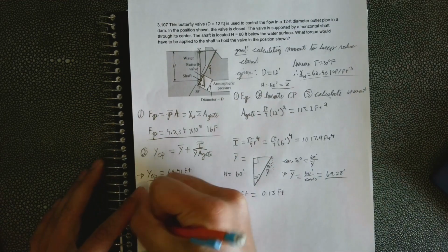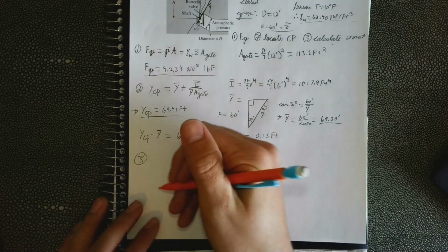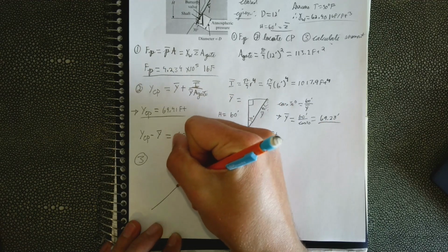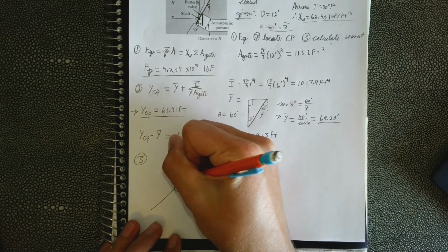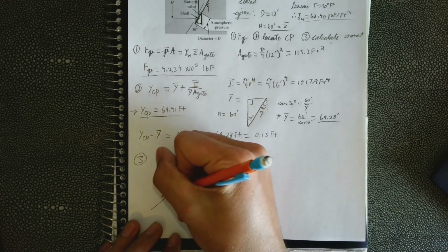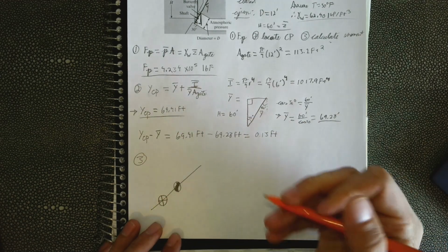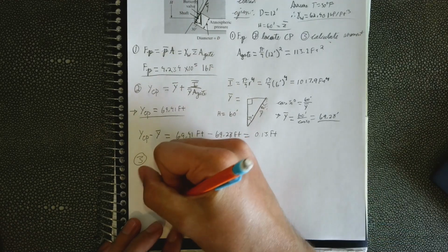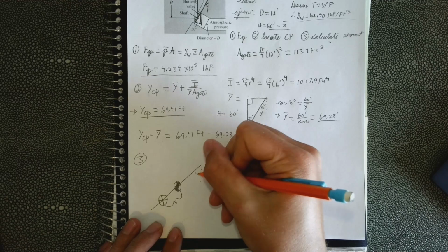So now our last step, let's calculate our moment. Let's draw a little FBD real quick. This one's really simple. This is our joint, or shaft, I mean. It also happens to be where our centroid is. And then our center of pressure we know is a little bit lower because the pressure is lower. We just calculate the difference between these 2 points at that same angle of 30 degrees.